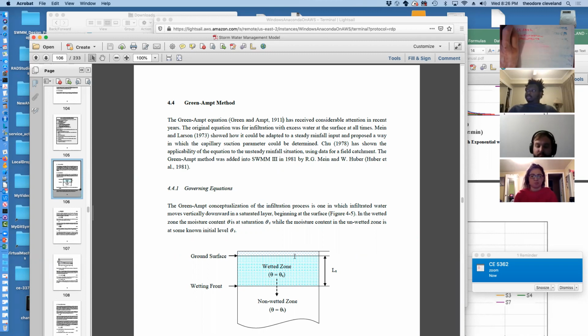And if you recall, Darcy's law is Q is equal to K, the hydraulic conductivity, times the area times the hydraulic gradient. The hydraulic gradient in the vertical in this picture, at the top, at the water soil interface, the total head at that position is elevation 0 plus however deep the water is, a couple inches.